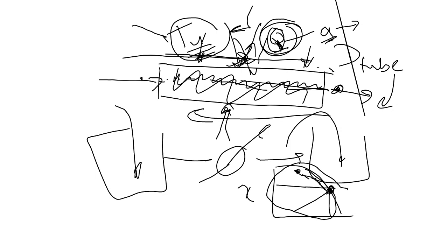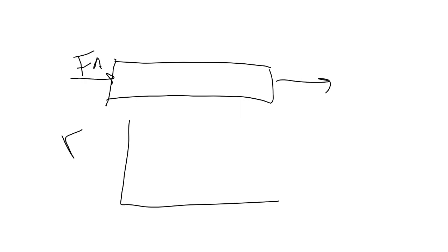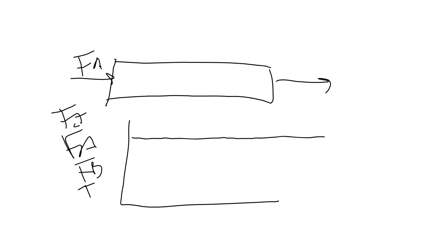So you can. Right, so let's just talk about this energy carrying capacity. Does the energy carrying capacity change along the length of your PBR? Along your PBR, you have an FI naught, and what happens is you have FA, FB, and temperature, and you've got this inert. So the inert flow rate stays exactly the same. Your FA is going to decrease, and FB you're going to see an increase. So this is FB, this is FA.